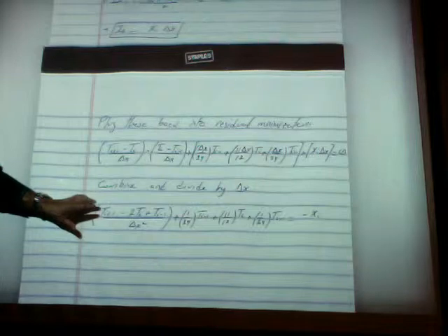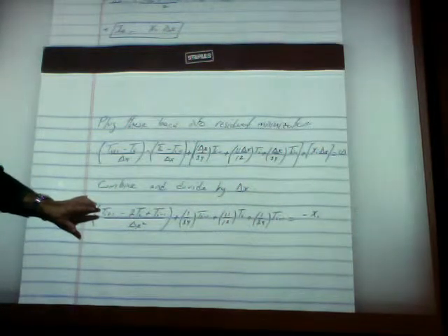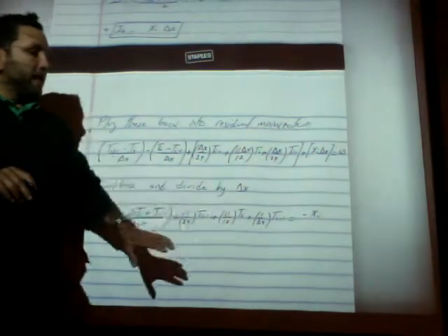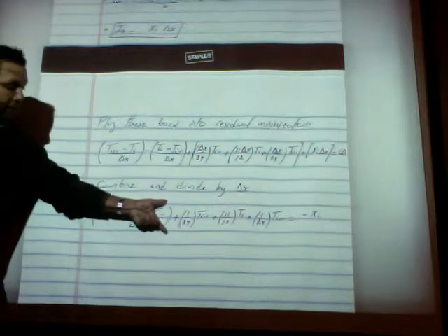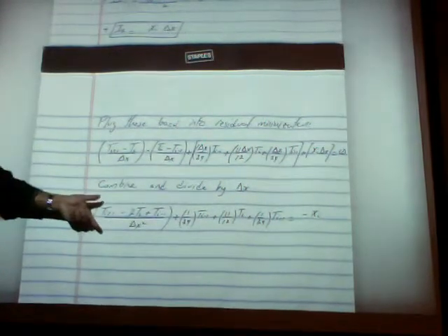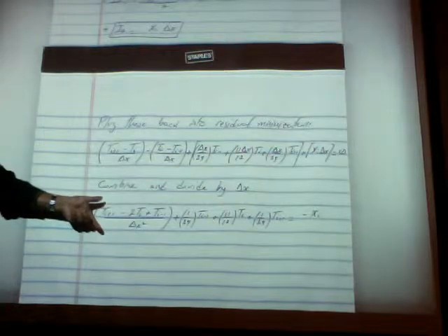And I don't know if you remember what we did last class, we had collocation with local support, which resulted in finite differencing. And in finite differencing, remember the equation that we're trying to solve has the second d2T/dx squared, the second derivative of the temperature. It has the temperature, and it has x, right? When we do local collocation, we end up with a finite differencing approximation of the second derivative, which is now identical. See, we ended up with the same approximation by doing the integration.